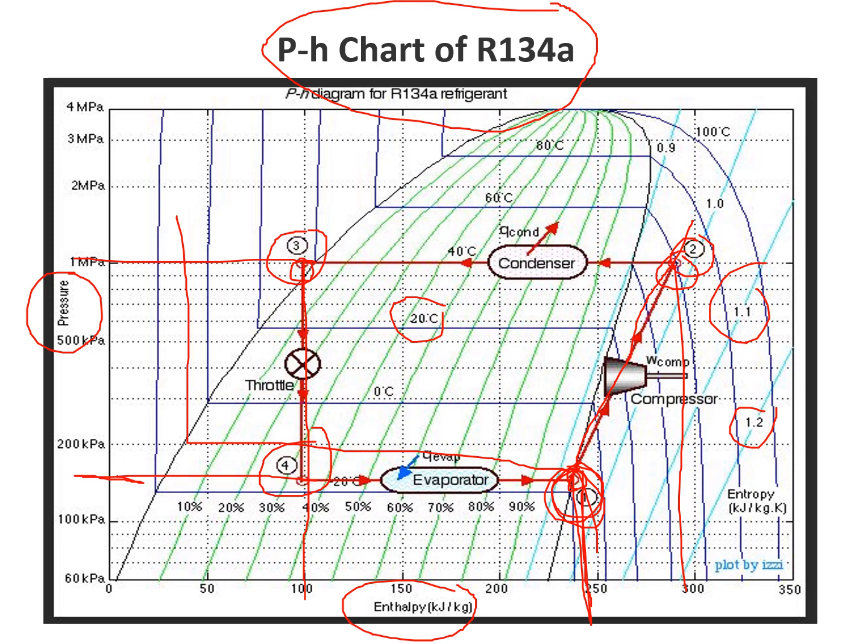How much refrigeration effect we get, that is H1 minus H4. How much work we did in that compressor, that will be H2 minus H1. Okay, how much heat is rejected in the condenser, that is H2 minus H3. So that is the utility of the pH chart to do the analysis of the vapor compression refrigeration cycle.